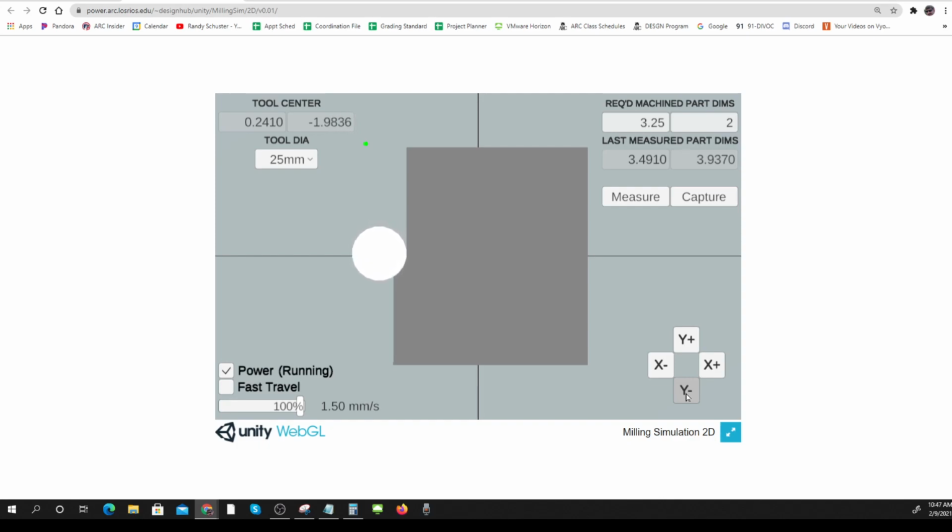After you're able to do this, we can have lots of discussions about choosing the right material size to start with, doing skim cuts, if you want a climb cut or a draw cut or a run cut, what size cutter to use to get a certain surface finish, what speeds to use. There's tons of stuff, but until you can get your size right, it doesn't make sense to try anything else.